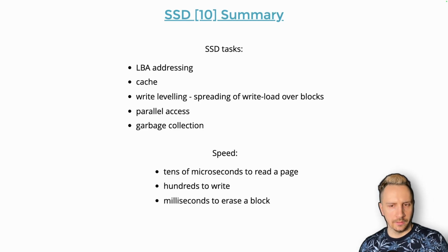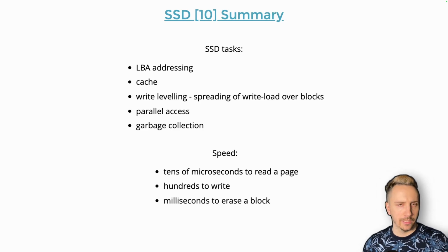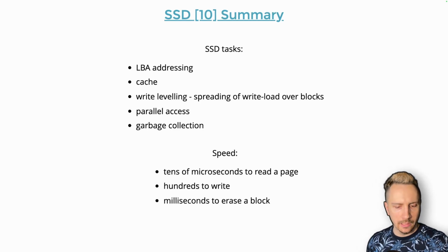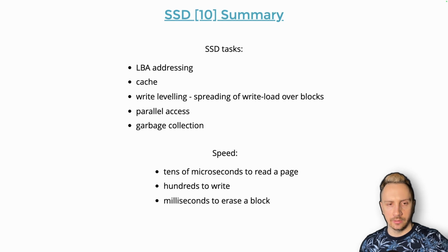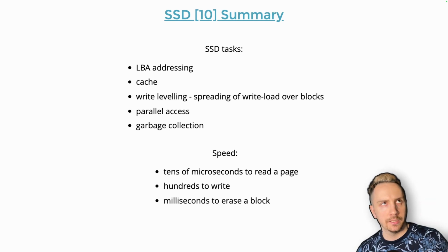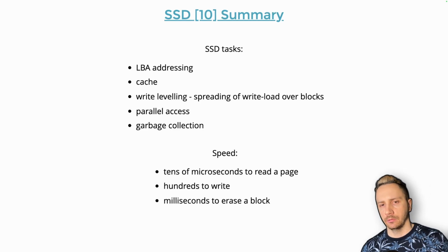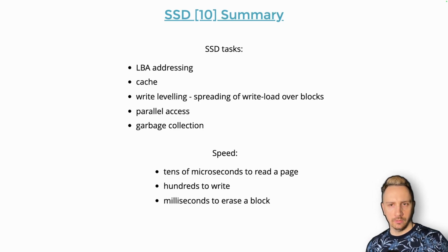Another job of the SSD controller is to keep in mind that SSD memory cells eventually get worn out and become unusable, as I explained. SSDs actually try to balance your writes in a way that the cells of the whole device get used evenly over time. So it's not like in one year half of your device becomes unusable and the other half is like new.